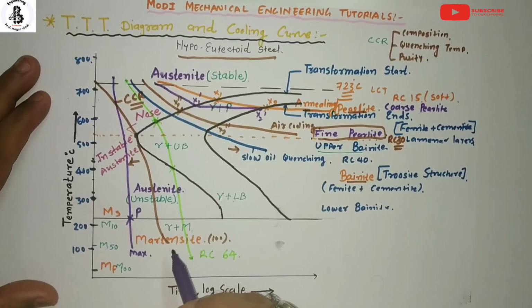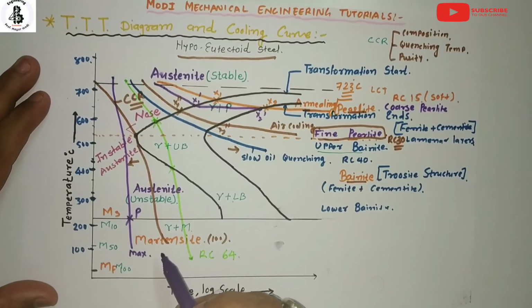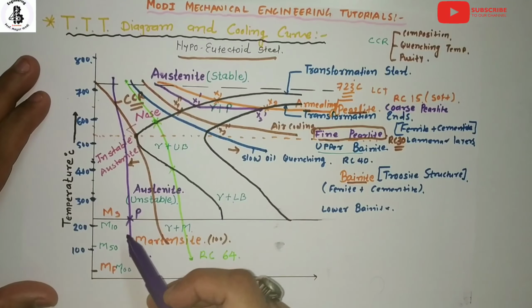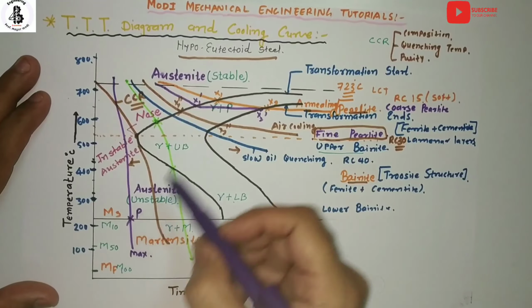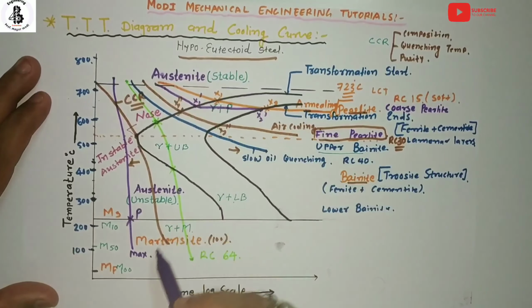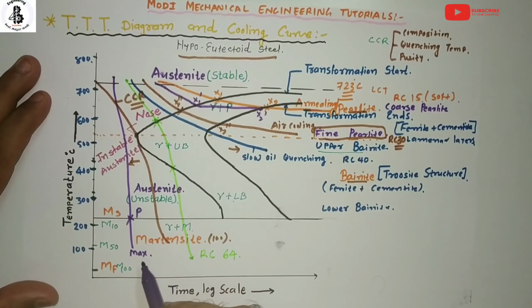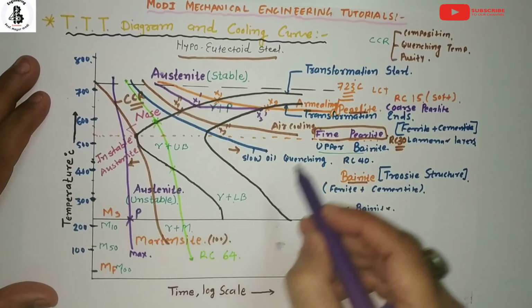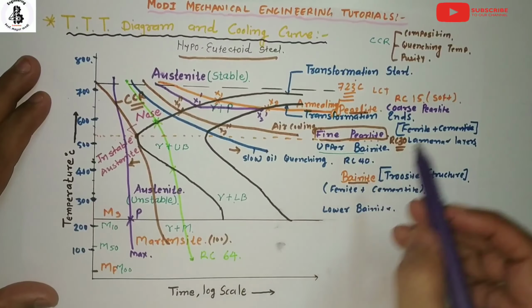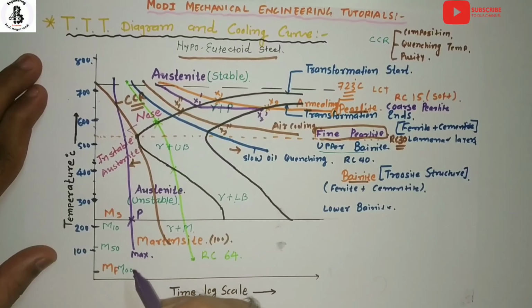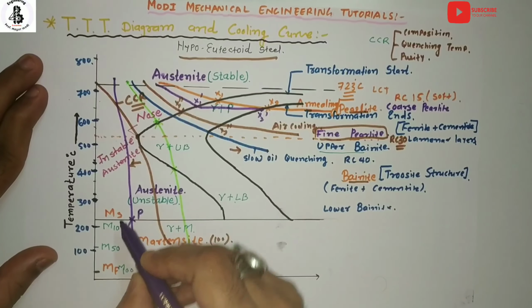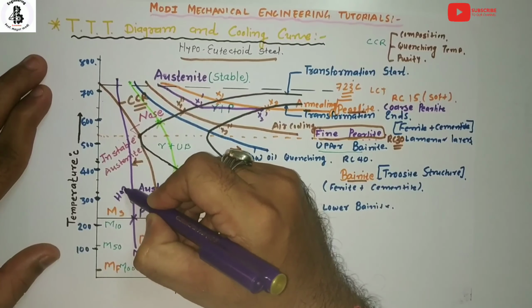Basically, all cutting tool materials are made by this rapid cooling process on steels, so that the austenite phase converts into the martensite phase. That gives the capability to cut any form of steel material, like pearlite or bainite structures. This rapid cooling process is known as the hardening process.